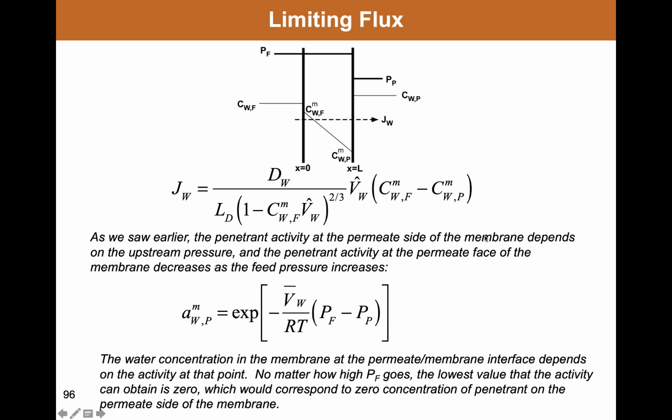Now, the activity of penetrant on the permeate side of the membrane has a relationship to the feed pressure that's shown here. Remember, we said that as the feed pressure goes up, thermodynamic activity of water in the membrane on the downstream side goes down. That means the concentration of water or solvent in the membrane goes down as feed pressure goes up.